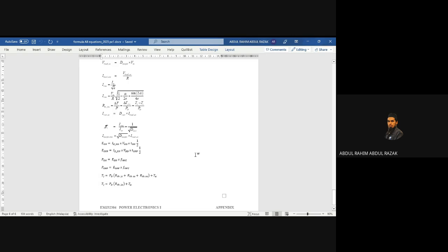Then we have issues whereby we are switching the converters at higher frequency, so we have to consider the frequency value of the converter, because we have to add up not only your losses due to conduction loss, but also due to switching loss. The contributing losses are during switch off and also during switch on. So how much power is absorbed by your switch is calculated by multiplying your switching frequency times the energy that it emits during off operation.